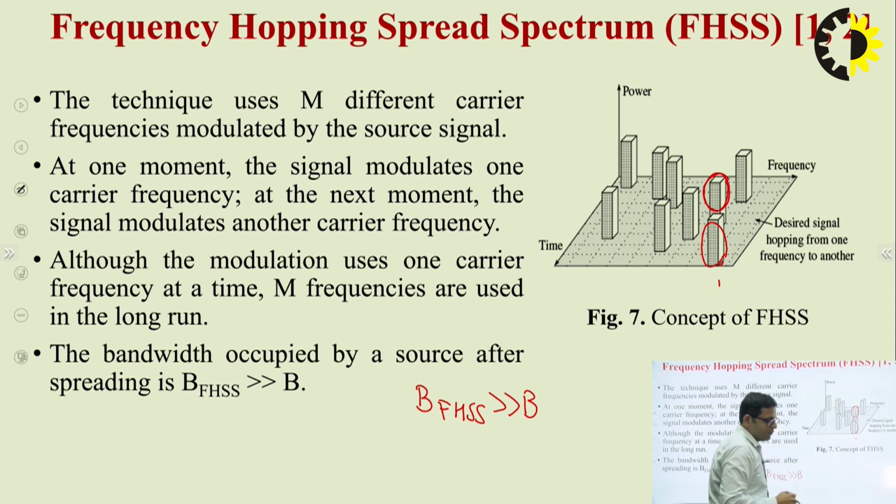So, in frequency hopping, we continuously change the carrier frequency so that the interferer or jamming signal can't predict our frequency of transmission, and we can easily save our desired signal from the intruder or enemy.